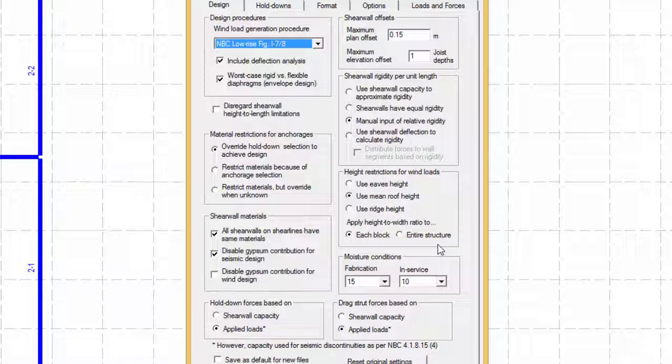A choice has been added due to the fact that there are currently no other methods available for roof block structures and shear walls other than to use the all heights method intended for flat roof structures, which may not be the case for the structure the user is designing. This allows the user to apply his or her discretion on what reference height should be used.